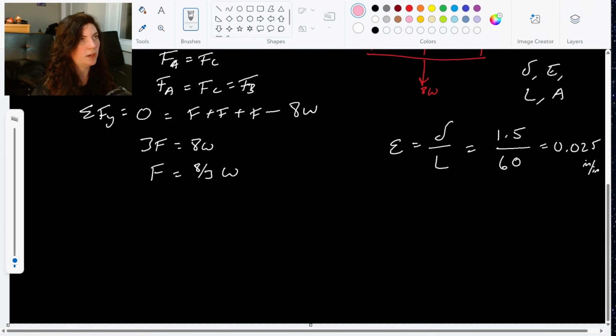I'm going to set up an equation with those. I'm going to say my slope, essentially, 60 minus 36, those are my 2 stress values, over 0.2 minus 0.0012. Those are my strain values that I was given.